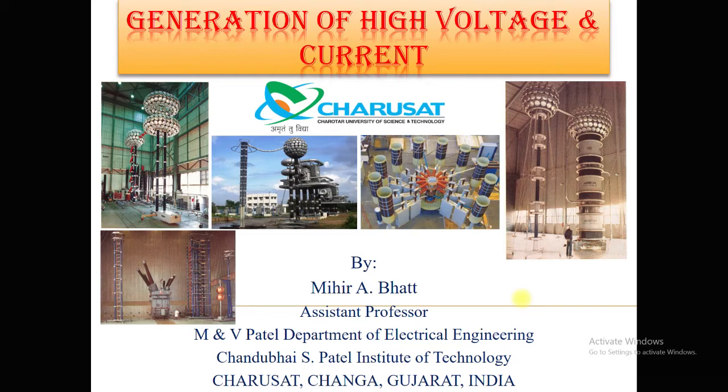Just think of the size of the generator which would be required to induce a voltage level of 220 kV. It is practically impossible to design generators which can give you the 220 kV supply, which is what you need to test the available insulators at 220 kV. So what could be the feasible solution? To connect step up transformers so that you can produce 220 kV, and by using that 220 kV you can test your insulation.